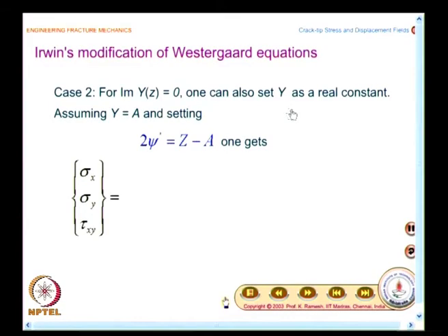When you had only one stress function, we were getting the solution and we carried on with it, because Westergaard in his paper also solved a variety of problems for which on y equal to 0, tau xy was 0. So people never looked closely at what kind of difficulties one would see in the case of a crack problem. When people compared the result with the experiment, they felt something more needs to be done. One of the earliest modifications was done by Irwin.